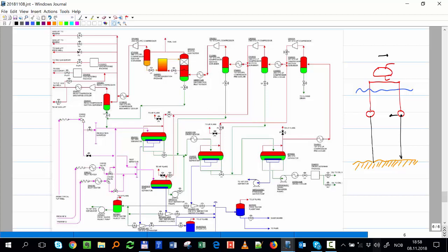When it's full, it's usually closed, and when it's clear, it means that it's open. So this well is producing to the main production train, the separation train, the three stages. Or it could go to test if I need to test the rate of that well.